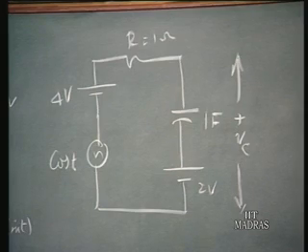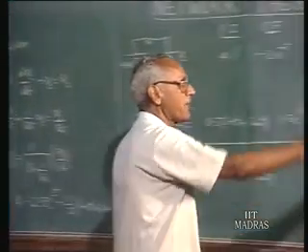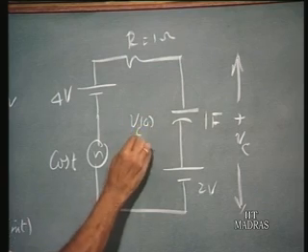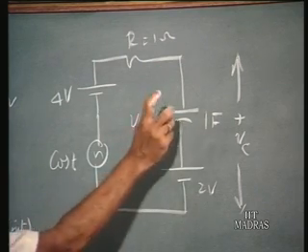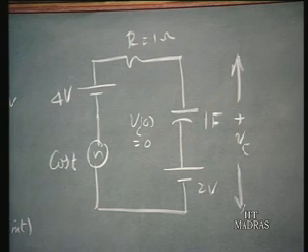So that is what we meant earlier, that you can superpose the total solutions with 0 initial conditions, because now this capacitor is assumed to have 0 voltage, because whatever non-zero initial condition was there, it is replaced by an equivalent source. Let us take another example.